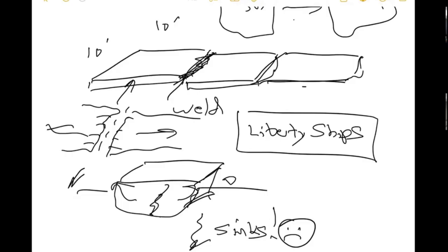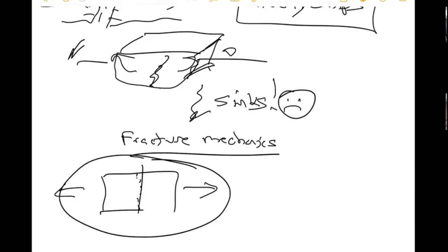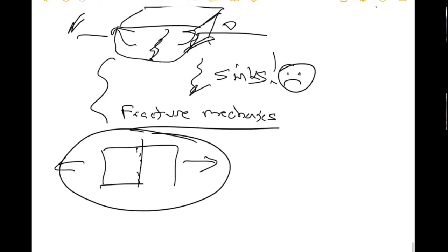Now when this thing gets stretched, these can rupture. So it's kind of like this situation: all these weird cracks, and it's getting pulled. Boom, the strength is much, much lower. They didn't design for this. Nobody thought about fracture toughness. They designed based on tensile tests and bending tests, the first type of analysis we talked about. Fracture mechanics arose because of that, and it was able to explain why this happened.